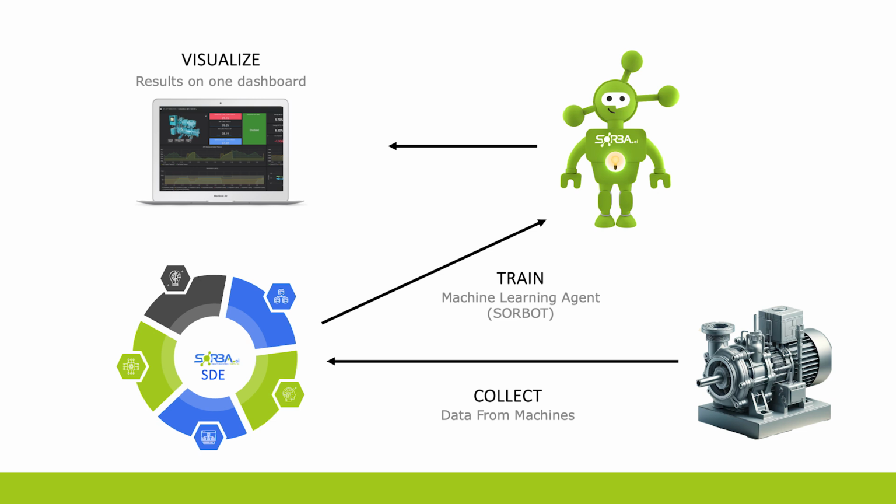The anomaly detection model, usually called clustering or unsupervised learning, takes data, tries to understand the data based on the clusters, and determines what is a baseline or normal behavior. For any abnormal behavior, the agent can then send an alert saying something is wrong, as well as what the inputs or variables are that are impacting that anomaly. So let's jump in. It's going to be able to detect abnormal behavior, where it can send that to the dashboard or to email or some type of annunciation that could alert someone to take a look at it.